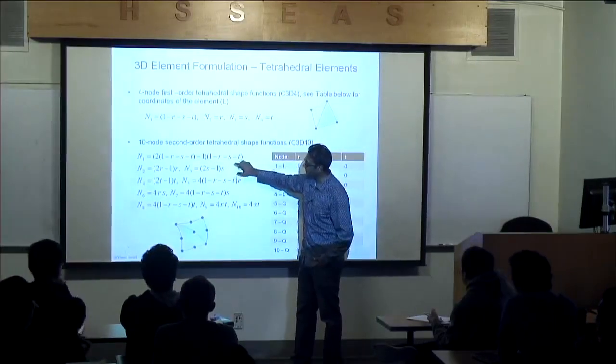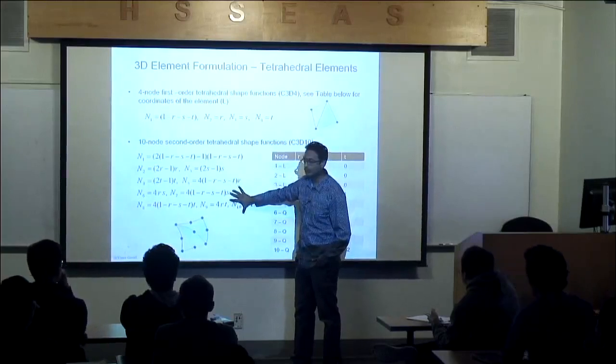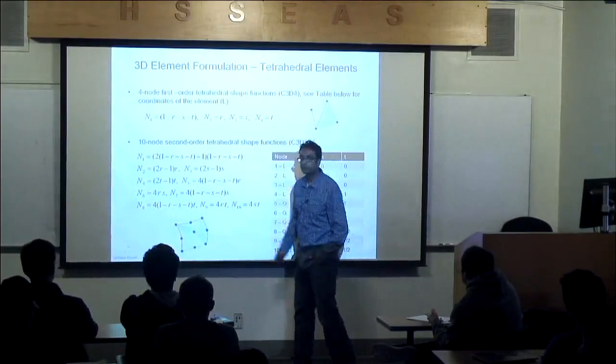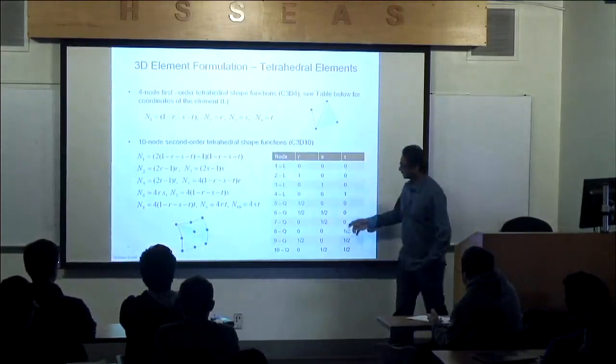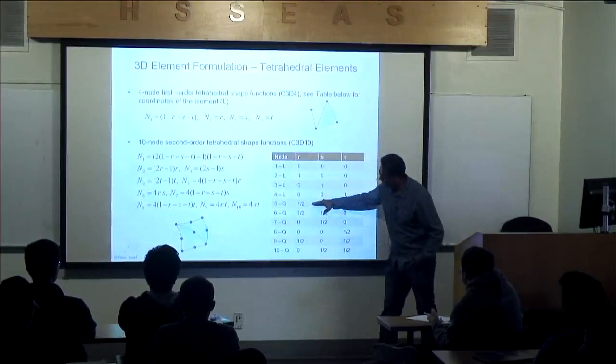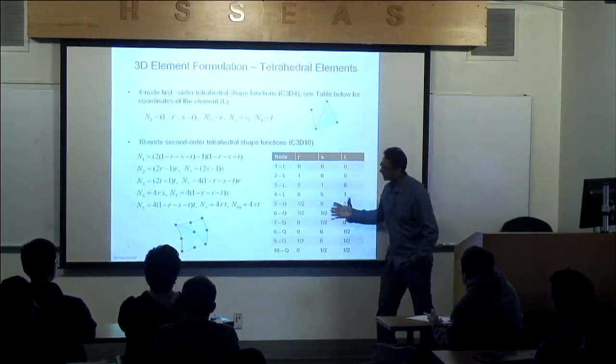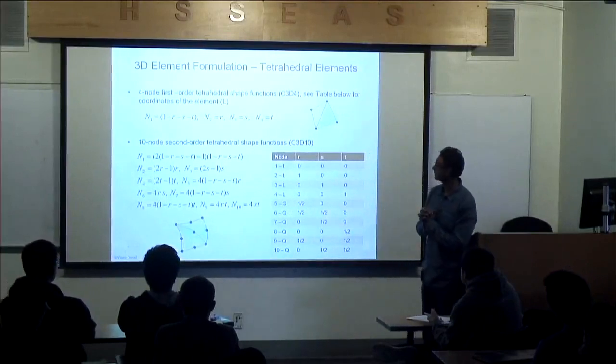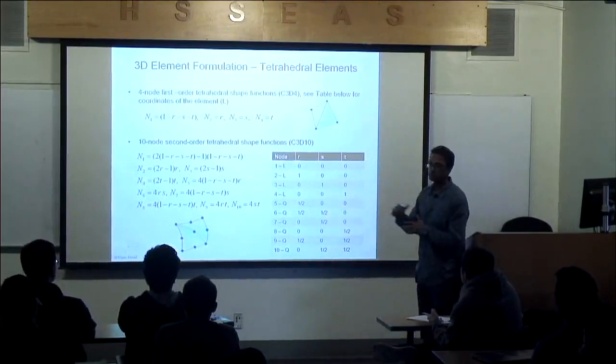These are the shape functions. There are 10 shape functions. You'll have basically an additional degree of freedom per edge, and whenever you see Q, those are the additional shape functions you need to make that tetrahedral element happen, this 10-node element happen. Okay, very, very good element too for 3D problems.